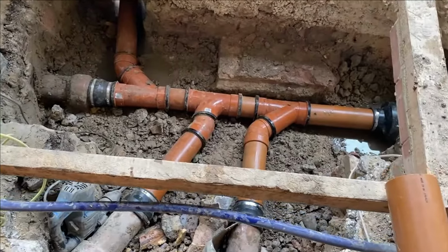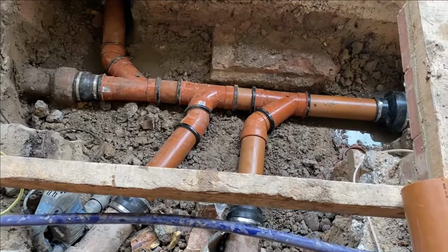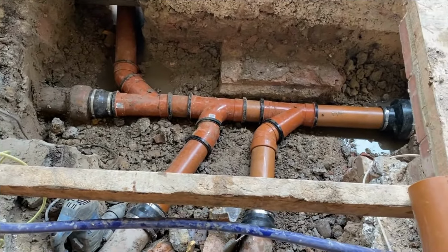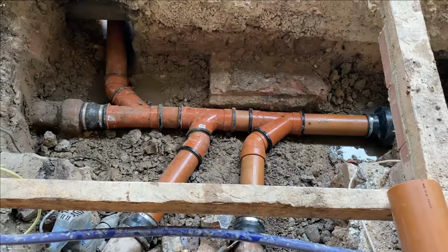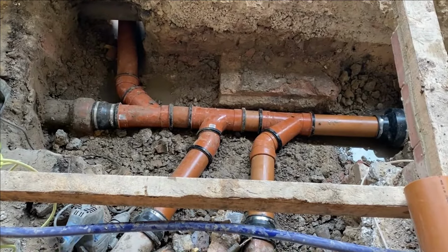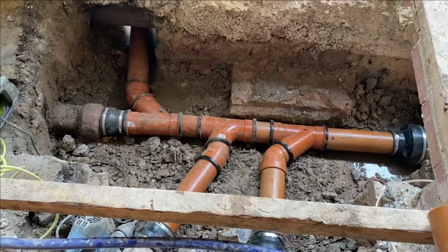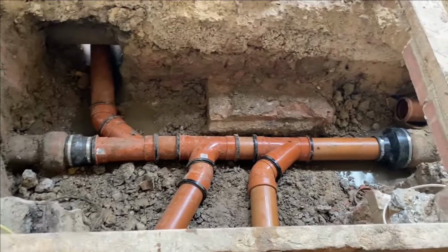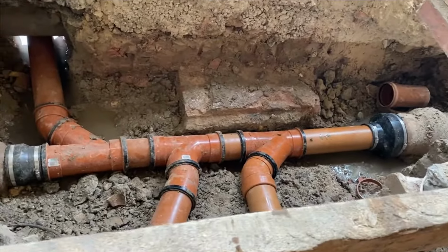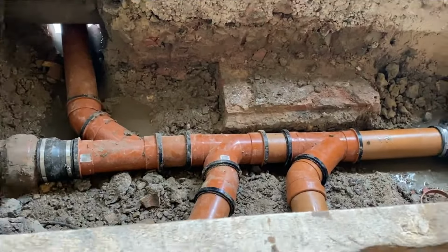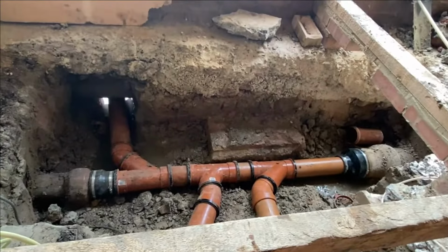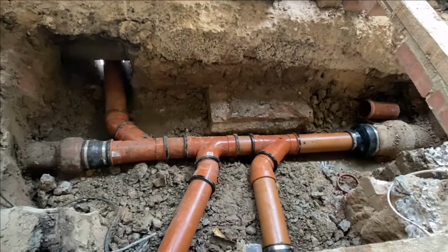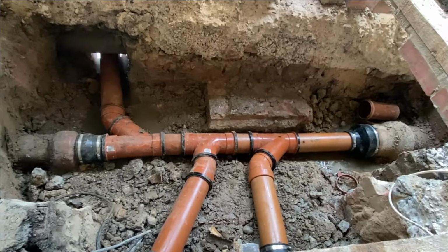And here we are with the final setup. So you can see that we've got the 2 connections coming from the house, which are at the bottom here. We've got the main sewer pipe which is running straight across, so we've cut that section out and replaced it with long-standing plastic, so that'll be good for at least the next 100 years. And then on the right hand side you can see the old clay pipe where we've connected into. So this is the new drainage arrangement, and the whole reason we've had to do this was solely to provide rodding access in the garden.